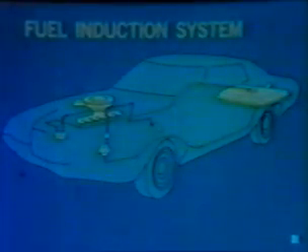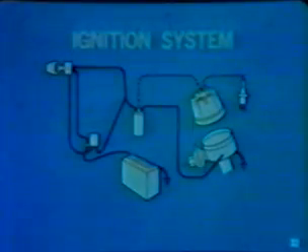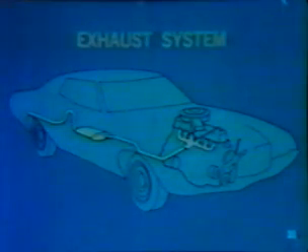An induction system provides the mixture of fuel and air for combustion. The ignition system attends to firing the compressed mixture from an electric spark at just the right instant. And the exhaust system disposes of the burned gases after they've done their work.